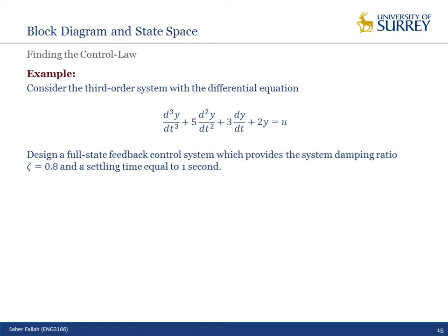Characteristic equation of what? The determinant of sI minus F. For which system? No, characteristic equation of what system? G(s) equals Y(s) over U(s), and then the characteristic equation is... Your answer is correct, but in state space format, not in the Laplace domain.